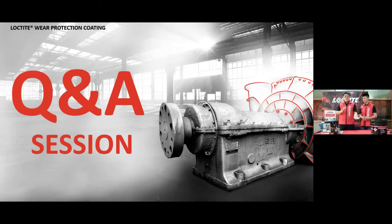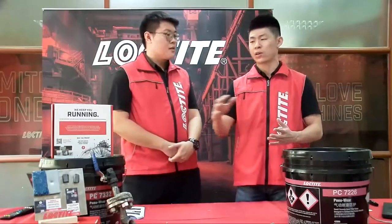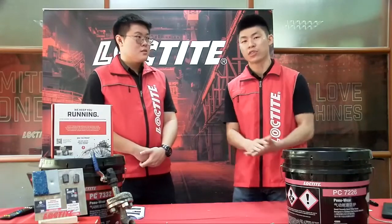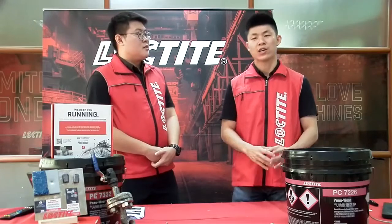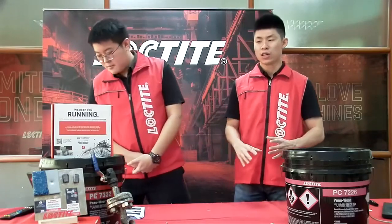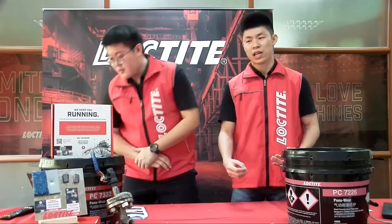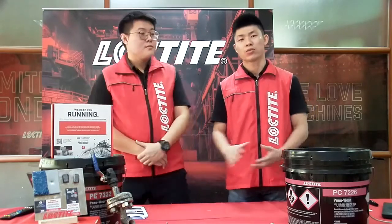Thanks, Kim. I hope we were able to answer this audience question. Next is: how long do you need to mix the two parts together? I think the audience is referring to 7218 or even 7226. I believe the question is how to make sure the product is mixed properly or evenly. All of our products, like 7332, 7218, 7226, come with the resin and the hardener in two different colors, either light gray and dark gray, or light blue and amber. As you mix the product and get a very consistent color, meaning it is mixed evenly, you can consider it properly mixed and ready to be applied to your surface.